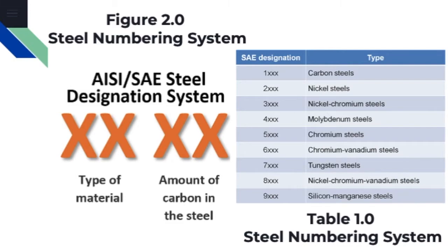If the first digit is a 1, it indicates a carbon steel. All carbon steels are in this group in both the SAE and AISI system. They are also subdivided into 4 categories due to particular underlying properties among them. Plain carbon steel is encompassed with the 10XX series containing 1% manganese maximum. Resulfurized carbon steel is encompassed within the 11XX series. Resulfurized and rephosphorized carbon steel is encompassed within the 12XX series. Non-resulfurized high manganese, up to 1.65 weighted percentage, carbon steel is encompassed within the 15XX series.